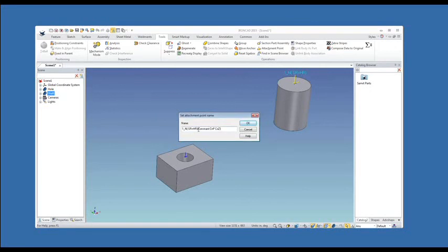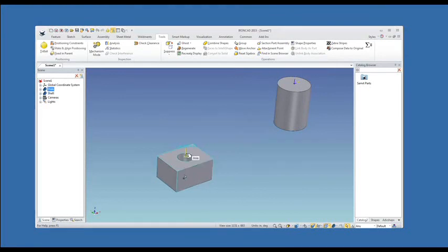So basically open another parenthesis, type in constraint colon, and this stands for coincident point, so CNP, and then coax on the z-axis, which is the long segment of the attachment point. So on drop, the shaft is going to be coincident to the point plus coaxial to the axis of the hole, which is exactly what I want. And again, I'm just going to copy all that and also apply it to there.